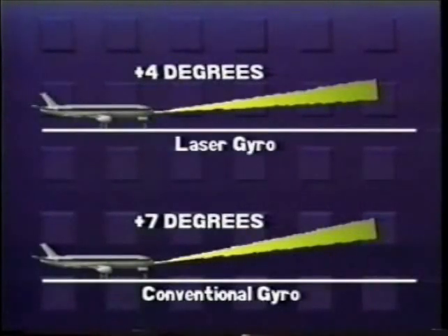If your evaluation of the takeoff area indicates a safe zone, leave the range set to 40 nautical miles and adjust the tilt control to +4 degrees for takeoff and initial climb-out. On aircraft that use conventional gyros, set the tilt to +7 degrees instead of +4 degrees. This additional +3 degrees compensates for the 3-degree acceleration error caused by precession of the gyro during acceleration. Precession error affects both pitch and roll during takeoff and climb-out.